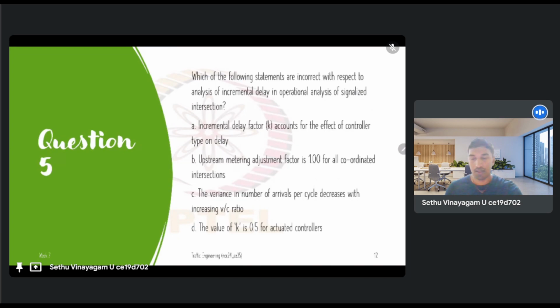Okay, so here this is coming from the operation analysis, right? So far we were looking at the planning analysis. So here we are looking at operation analysis, and within that the delay analysis, right? So within delay, we call this control delay because we are analyzing delay due to a traffic control system. That will have 3 parts, D1, D2, and D3. D1 is your uniform delay. D2 is the incremental delay, right? And D3 is delay that is caused because of initial queue that may be present.